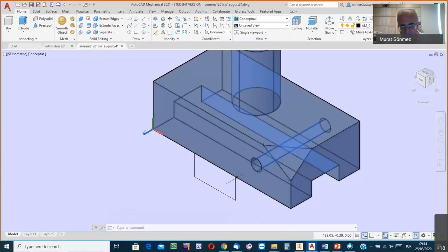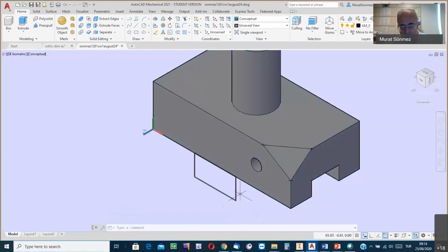If the relative displacement is in the negative sense of the coordinate axis, don't forget, write the coordinate value with a negative sign. Yes, I want to make this point clear. Shall you input width and height? Then no problem. But of course, if you know the trick, click on Tab after writing the width.